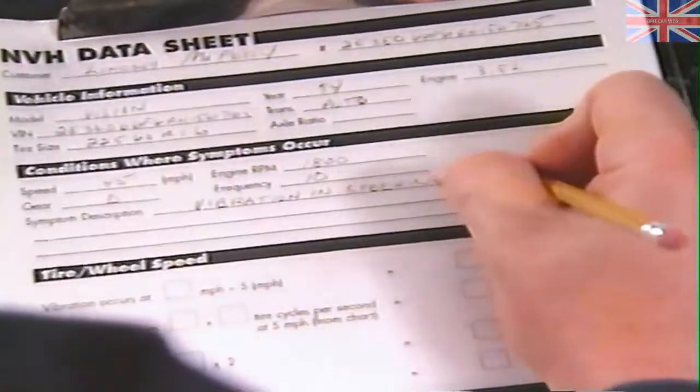Gathering information and thoroughly testing will allow you to determine related symptoms. You should be able to determine if the noise, vibration, or harshness is engine speed related or vehicle speed related. In most cases, you'll narrow the trouble source down even further. It's important that you clearly understand how to determine related symptoms. So before we go to the next step, let's test what we've learned with a review question.